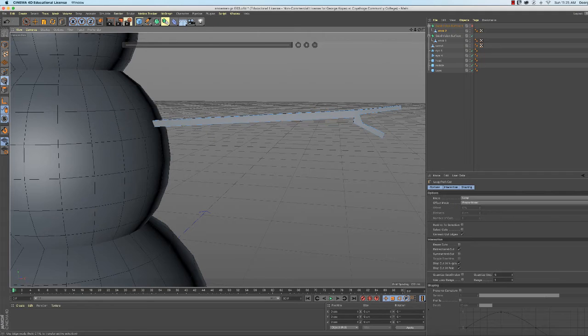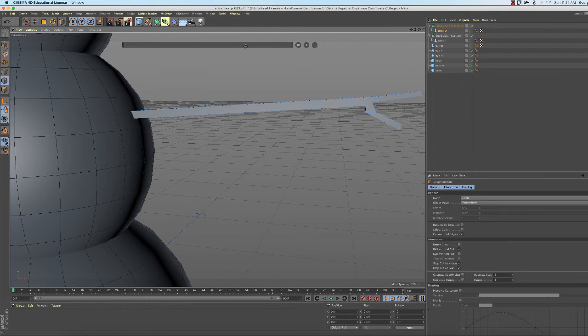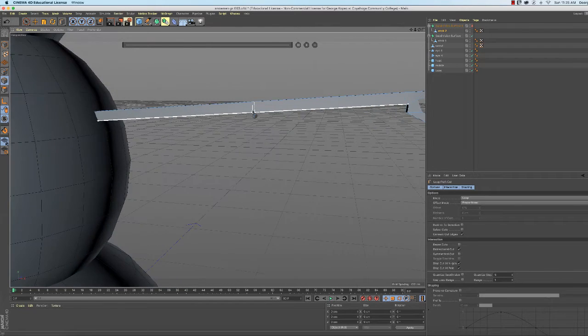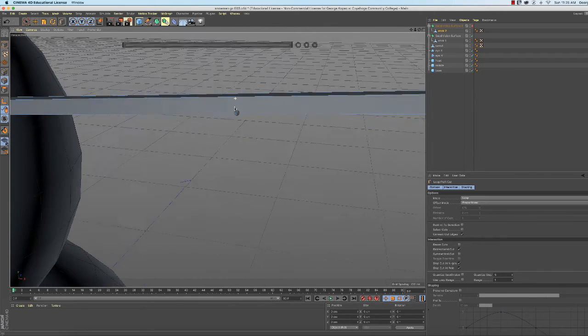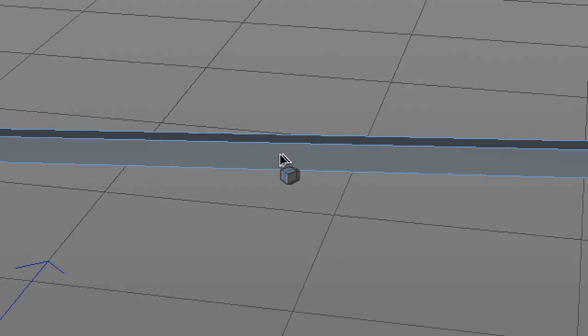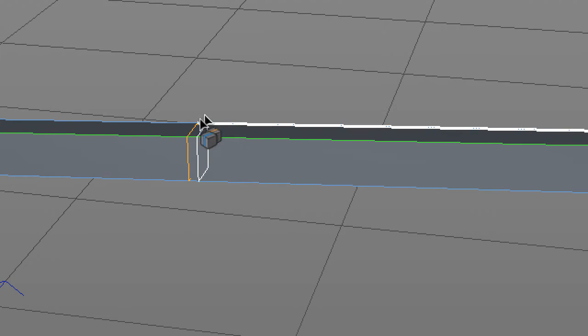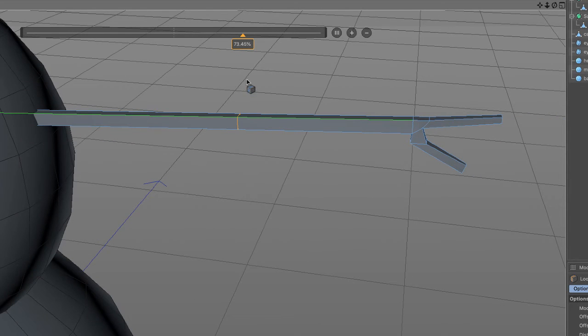So let's click edge mode, have the loop path cut tool enabled, and what happens is when the loop path cut tool is enabled, this slider is visible. There's nothing to slide right now because we didn't make a cut yet, but all I can do is hover over the object, and let me zoom way in so you can see this clearly on the screen. It makes this loop, lo and behold. No surprises there. And anywhere I click, it makes a set of edges there that I can adjust and play around with.